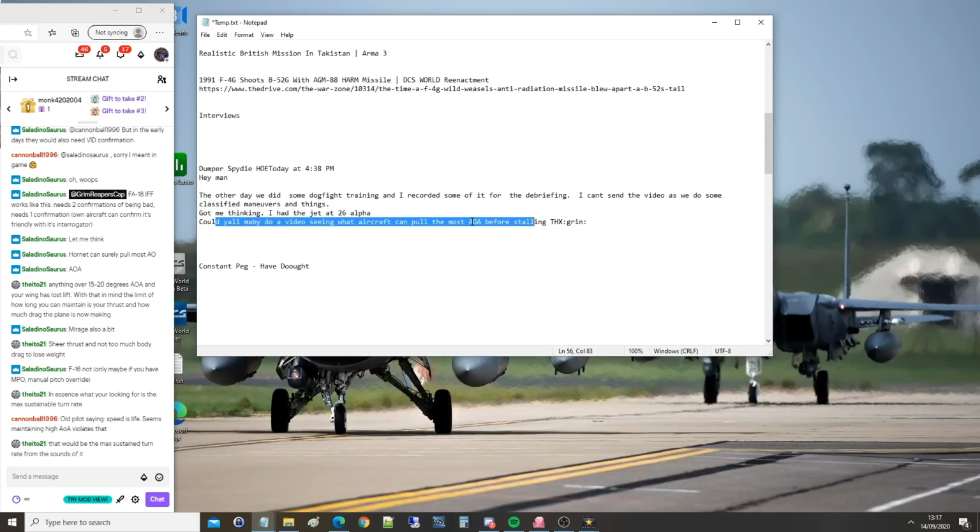The next most important thing, I think, is going to be a culmination of other attributes, which is going to turn out to be minimum radius of turn. So instead of how quickly you can go around the circle in terms of degrees, how tightly you can turn. Let's say that you've got the same degrees per second, the same turn rate as your opposing guy, but you can turn in a tighter, smaller radius. This is something I've learned more recently from doing more serious dogfight analysis: the guy with the smaller radius turn will always have the advantage because he can always control the fight. I can't explain that in a geometric sense because I'm not smart enough. You'll probably have to go to Lemoyne or someone to explain that.